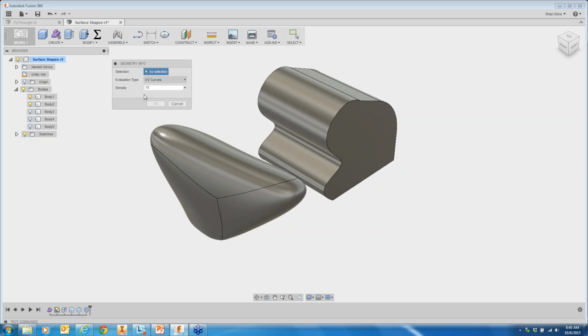So that would define a line along one edge, and then I would have a point at 0, 0.5, another at 0.5, 0.5, and one at 1, 0.5. And so I would define another line, and then finally 0, 1, 0.5, 1, and 1, 1. So there are these 9 points defined in this rectangular grid. I got the minimum and maximum values, defined these points, and then I pass that to this evaluator and say, here are 9 points in UV space.